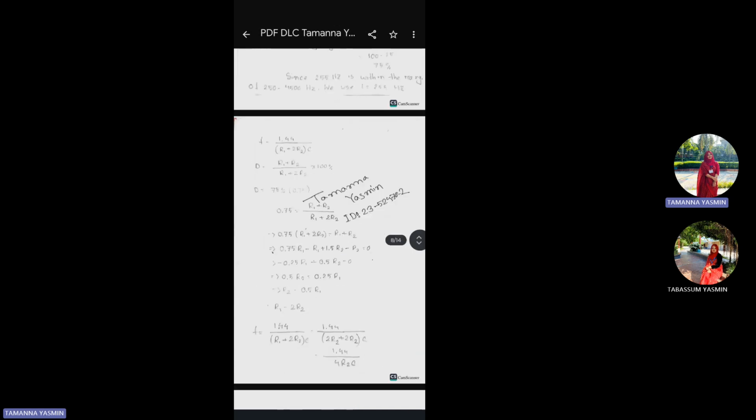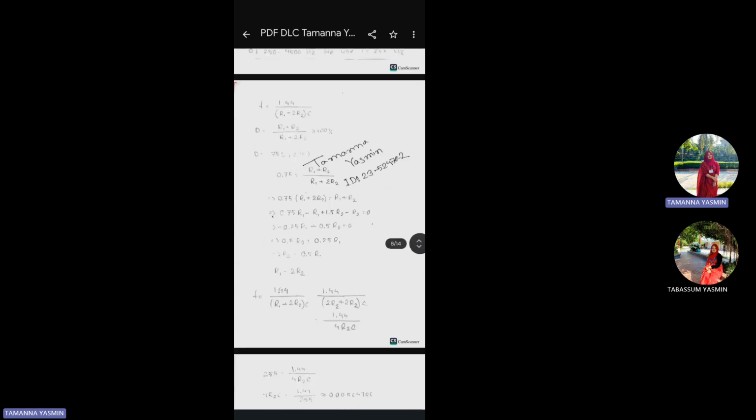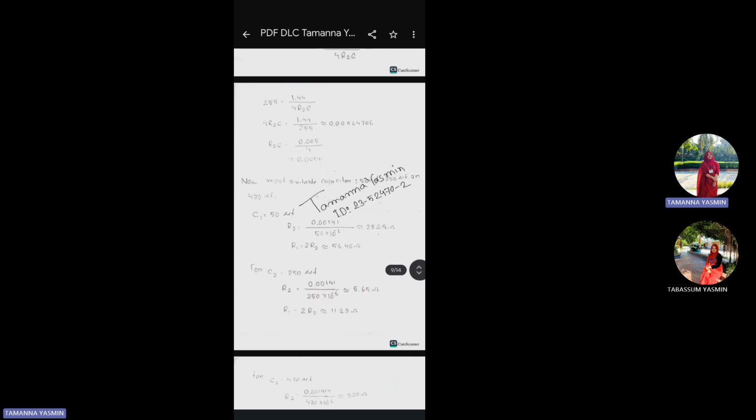And for question 4, with my ID number, my O is 0. So it is replaced with X plus Y plus Z, that is 27. So my P is 25. This gave me a target frequency of 255 Hz and a duty cycle of 75%. I chose a 50 microfarad capacitor for the option, as it would lead to the most practical resistor values.